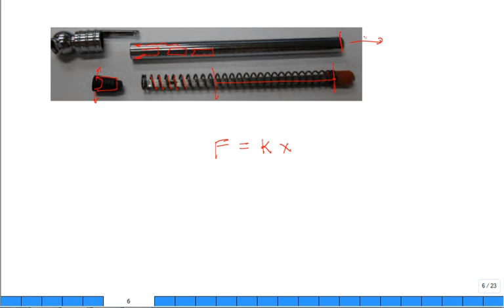So what happens is you have the area, the force, you get the pressure, and so by having a calibrated stem, the stem also is sitting here connected to the plunger, and the stem gets pushed out. There's a little reddish type of cap of plastic that adds a little bit of friction such that when you take it off the tire, the spring will go back to its unelongated length, but it's not going to pull in your meter. It's going to stay out. That's why you measure it, you pull it up, you read it, then you push it back in to reset.